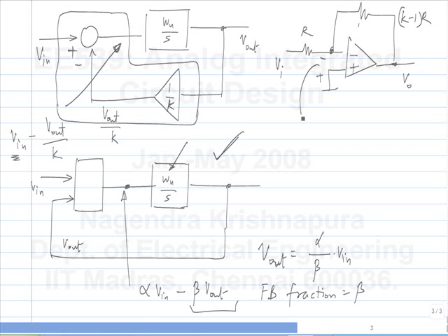So what is the input to our integrator here? With this sign. What's the input to the integrator? So the voltage at this point will be a linear combination of Vi and V0, and the weight will depend on the resistors. Okay. And VID is defined to be opposite of that, right?